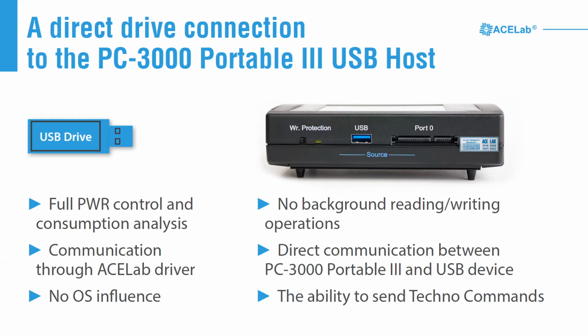the operating system. And of course, even if you connect the drive through a USB port, it will be possible to send some low-level commands in technological mode. Before we released this solution, if we are talking about USB, the native USB WD, Toshiba or Samsung HDD, you had to find a donor drive, swap the SATA PCB unit, swap the ROM chip, unsolder everything, and after that you would get a SATA drive that you could communicate with and work on.